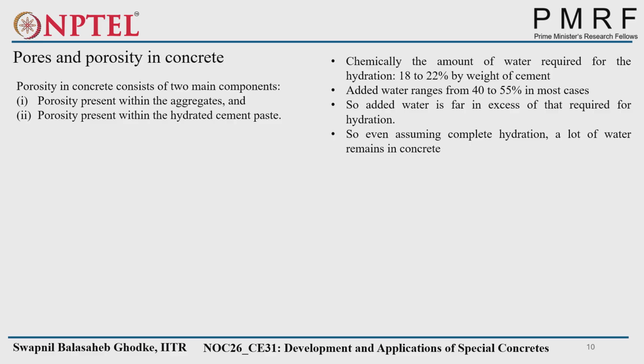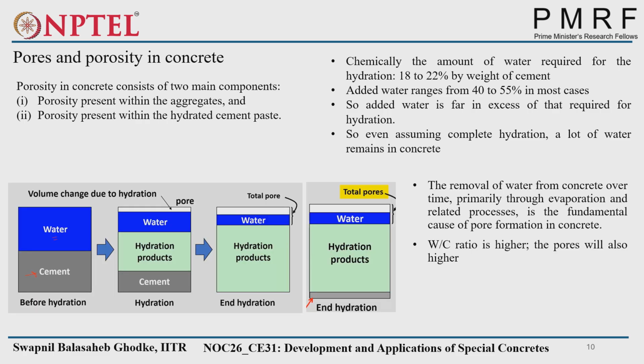That's why increasing the water content makes strength go on decreasing, because of that extra amount of pores. Understood? So that's why if you see ultra performance concrete, you will see the water content is very less, almost zero point 0.2 to 0.23.